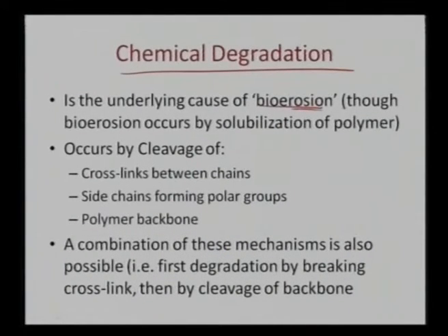So chemical degradation is the underlying cause of bioerosion. Though bioerosion can occur by the solubilization of the polymer, the main reason behind bioerosion is nothing but chemical degradation, and chemical degradation is the occurrence of cleavage. It can be the cleavage of cross links between the chains, it can also be the cleavage of the side chains which form the polar groups, or it can also be the breakage of the polymer backbone itself. And again there can be a combination of these mechanisms.